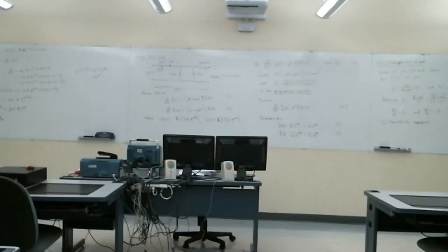And then the conductance is 200 microsiemens per meter. Now remember, this is the conductance between the outer conductor and the inner conductor. Ideally, we would want zero conductance between those because that would be an infinite resistance. So the smaller each of these are, the better. Ideally, we would have zero resistance, and zero conductance between the two conductors, which would correspond to an infinite resistance.